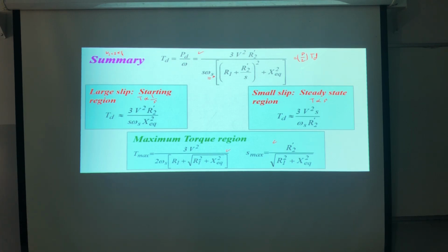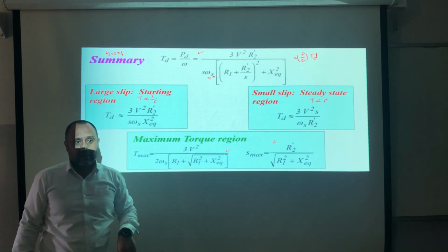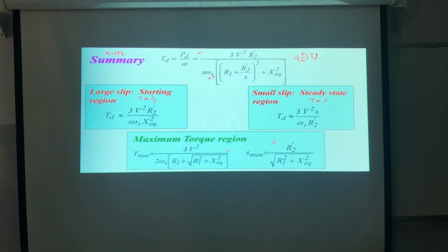The second thing, you should understand how I calculated the developed torque. Because imagine I'm changing the configuration and connecting external resistance to the rotor, or connecting an external supply to the rotor, like a double feed induction generator. The double feed induction generator is an induction machine where I can also inject a voltage in the rotor. But if I need to inject any voltage on the rotor circuit, I must respect the frequency of the rotor. Otherwise, I will cause a short circuit current.